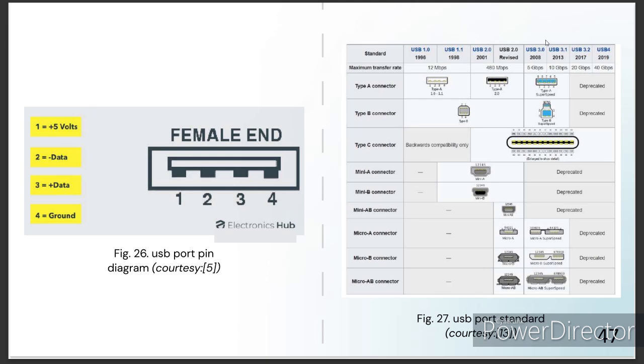Different generations of USB. USB 1.x. USB 1.0, which was introduced in January 1996, called for signaling rates of 1.5 Mbits per second. Due to timing and power restrictions, extension cables were not permitted. Before USB 1.1 was released in August 1998, a few USB devices were commercially viable. The first generation of USB, known as 1.1, saw widespread adoption and gave rise to what Microsoft called the legacy-free PC.